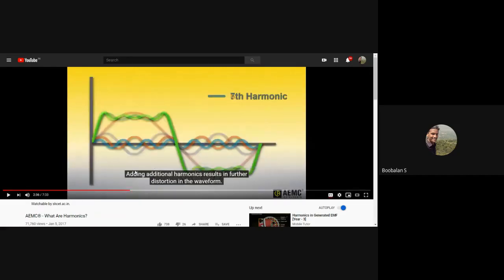So these are the different kinds of harmonics: third order, fifth order, seventh order, ninth order, 11th order. These are called odd harmonics. There will be even harmonics also, right? These are the harmonics which will be developed or injected into my electrical network due to the different kinds of operation of my switching devices. How that switching device is changing cyclically, there will be a number of cyclic methods. Based upon that, a huge injection of harmonics into the electrical network is possible, right?